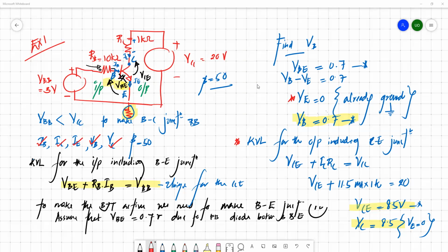What are the operating regions? What are the maximum currents and voltages this particular transistor can handle? Everything should be there, including how this transistor is affected by temperature. In addition to that, you can easily get the beta value from the data sheet. Then you design this VBB and VCC based on the transistor parameters.